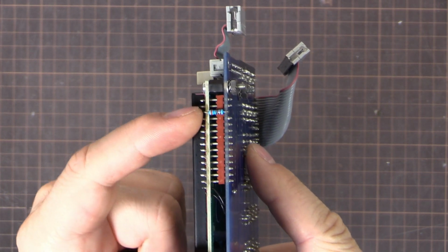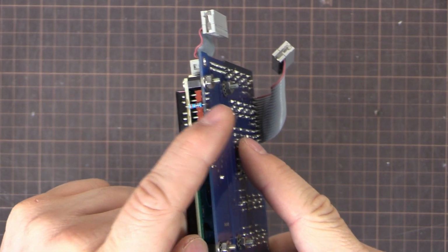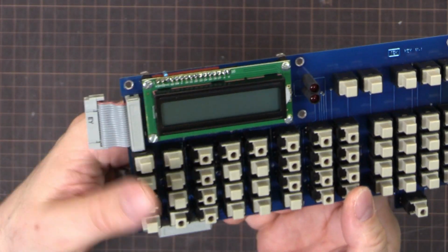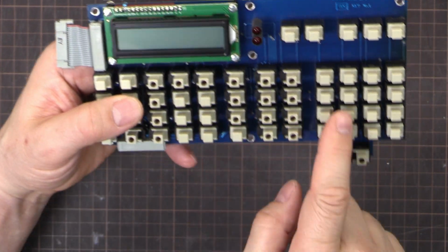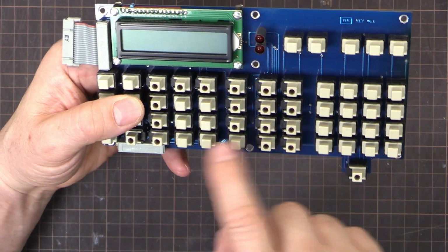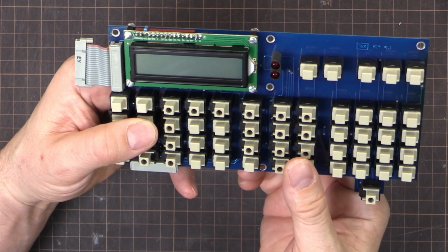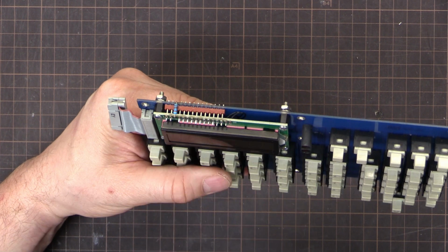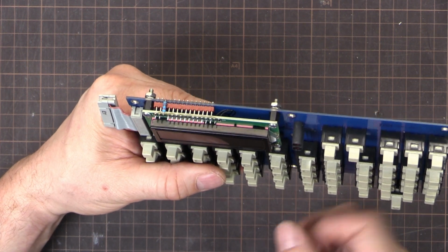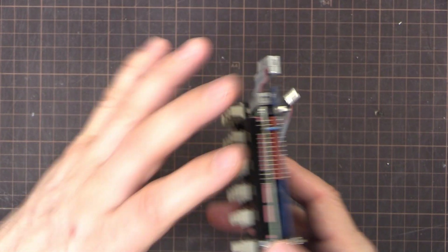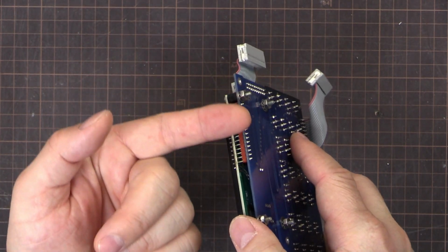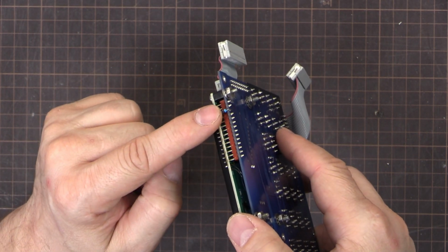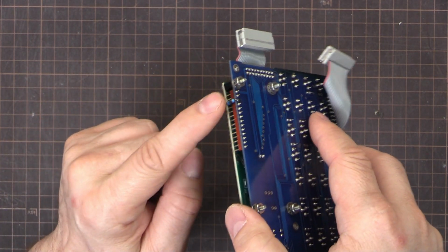Just loop it from one side around the outside and back in again. And that sits there nice and flat. And it brings that contrast setting to dead center. So at 50, from 0 to 100, this is perfectly in the center of its contrast range. You might have to change that a little bit depending on your screen, but 3.6K should be a good starting point. I'm also going to put a little bit of Kapton tape on the housing where this goes in, because that's an aluminium piece that goes over the top, and it is pretty close. So I'll put a bit of Kapton tape inside there so that resistor doesn't rub.